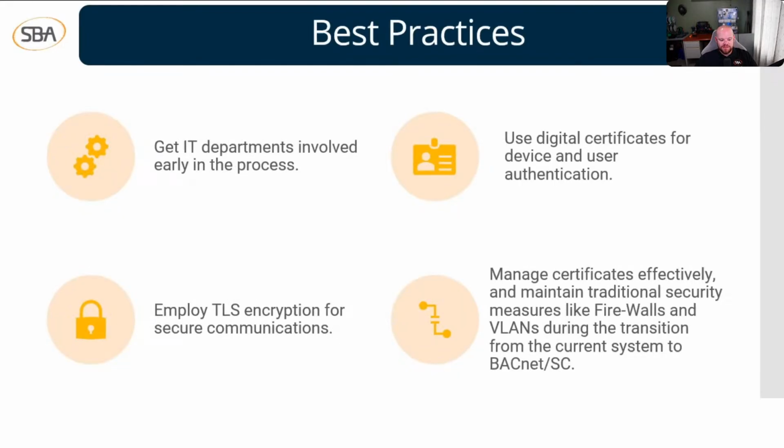All right, and then we look at getting into some best practices. Some best practices that you need to remember when you're upgrading from these old systems to BACnet SC is to get the IT departments involved early in the process. This ties in with what I was talking about in the case study about the job scope and IT people understanding the job. Honestly, probably before you even sit down in a meeting, start having talks with them. Let them know where your head's at, what your ideas are, just so they're in the loop and on the same page as you. That's really, really important.